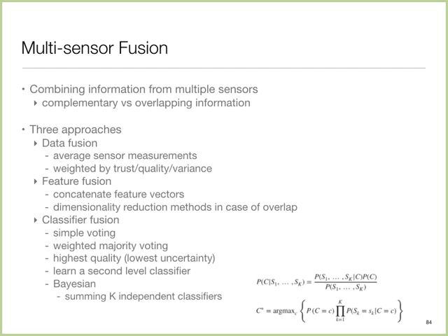So I'm forcing each sensor to reach a hard decision and then literally combining them. More generally, people like to use this intermediate one, which is soft decision making. We are combining the results so that even if a sensor may provide some partial information, like maybe I'm trying to recognize an individual, and one sensor can sense the height and the other one can sense the gait and the third one can sense something else, by combining them together, I will generally have a better sense.